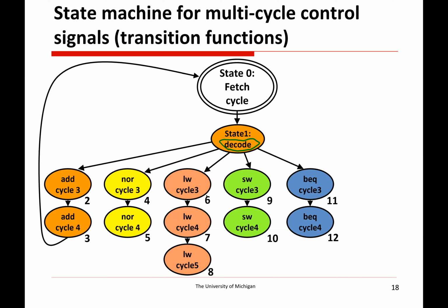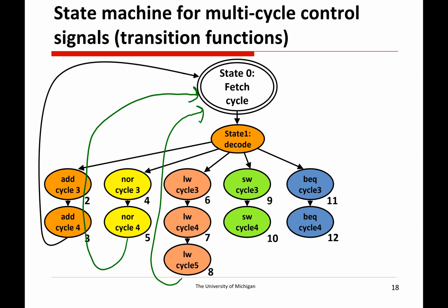And then we'll split off into a different state machine for each individual instruction. Most of these are going to take 2. Loads are going to take an extra cycle. We'll see why, but it makes sense given that before, load word was the longest instruction. And yeah, we'll go through each of these states and see how that goes. Once we get to the end of each instruction, each of these, even if I haven't shown it, has an implicit cycle back to the fetch instruction. So we have this endless process of fetching instructions, executing them, fetching the next instruction.